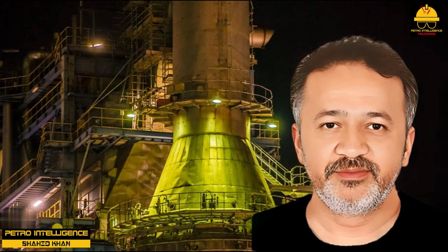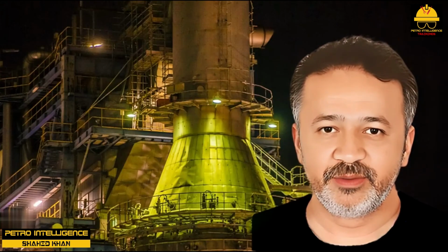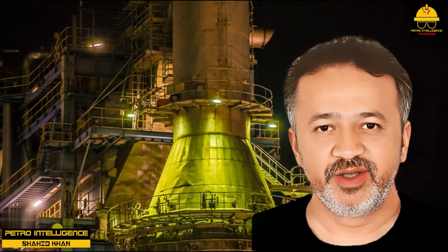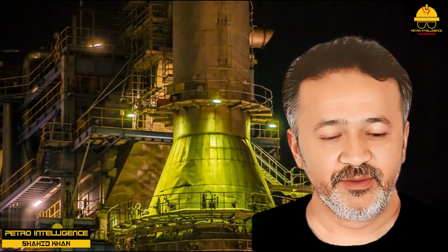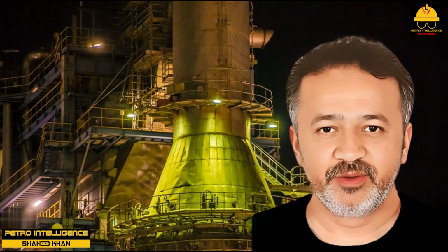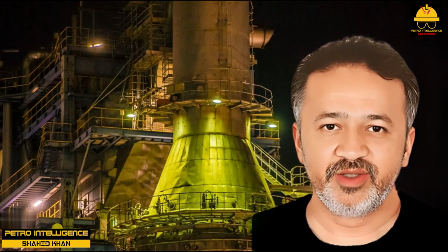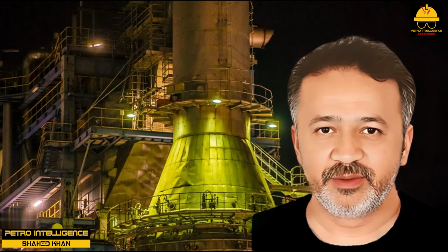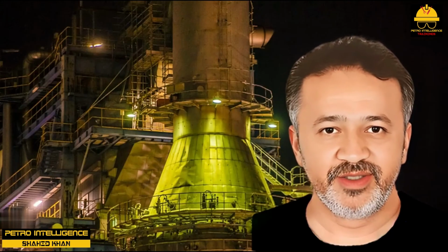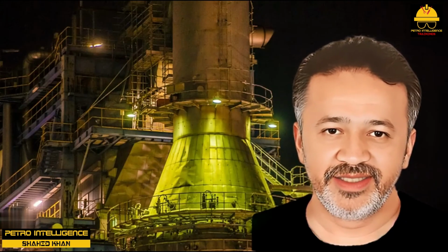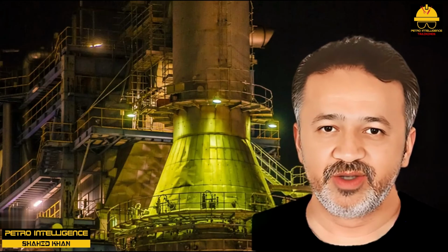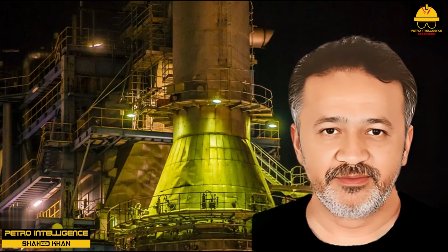Lighting burners. Before lighting burners in a piece of fired equipment that has been idle or offline for any time, or whose burners have become extinguished during operation, it is vital to first purge the firebox of hydrocarbons and combustibles or explosive mixtures. Here is a method as outlined to me by a prominent burner manufacturing company.